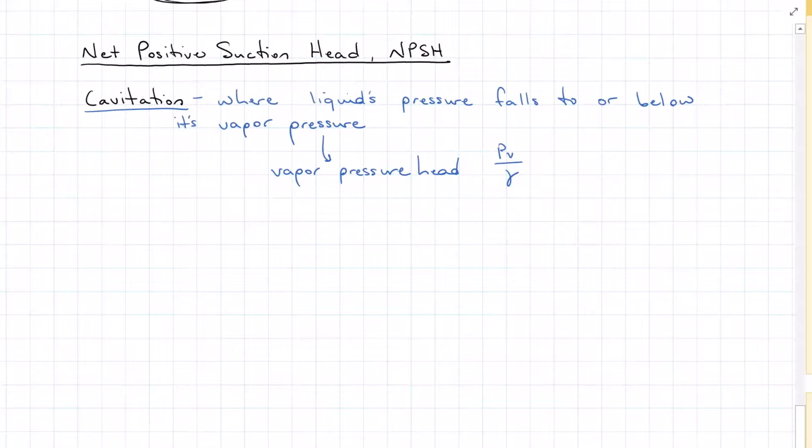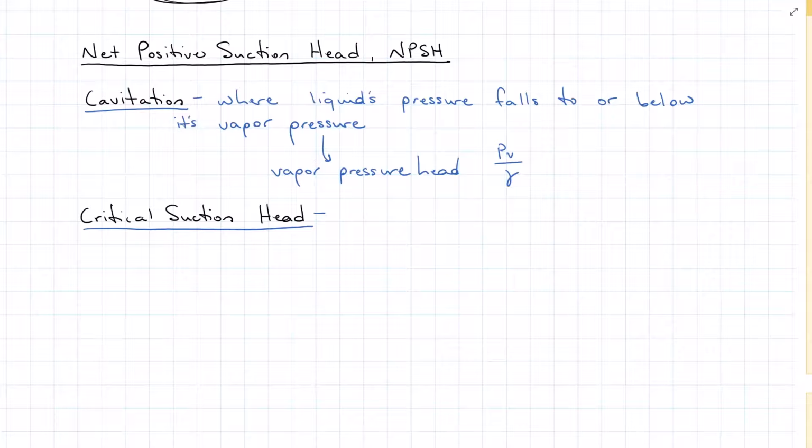Next, we need the critical suction head. And the critical suction head is the absolute pressure and velocity head coming into the pump.